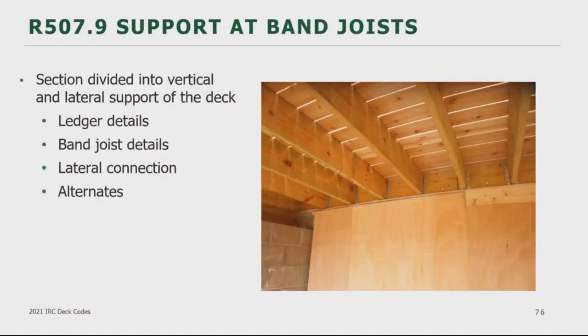R507.9 will bring in requirements for support to the band joists of the house itself. This is not a band joist on the deck. Again, this is for attachment to the house when it's required by R507.8.